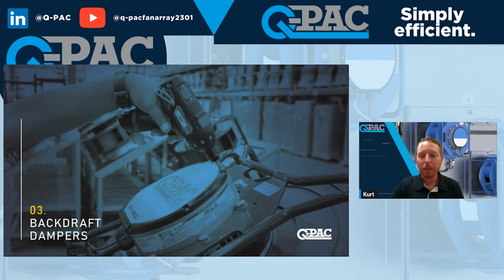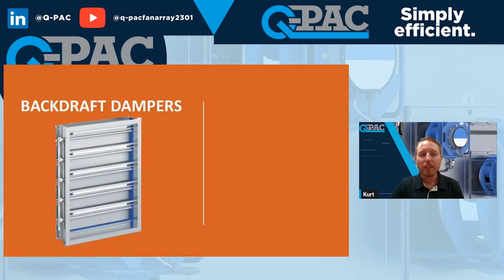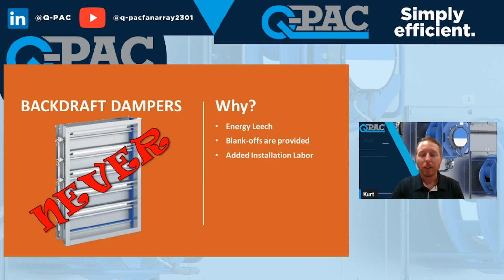All right, backdraft dampers. So when's the best time to use a backdraft damper? I say never. The reason why is it's an energy leach, right? We assume 0.2 inches of additional static pressure every time you add backdraft dampers to our system.